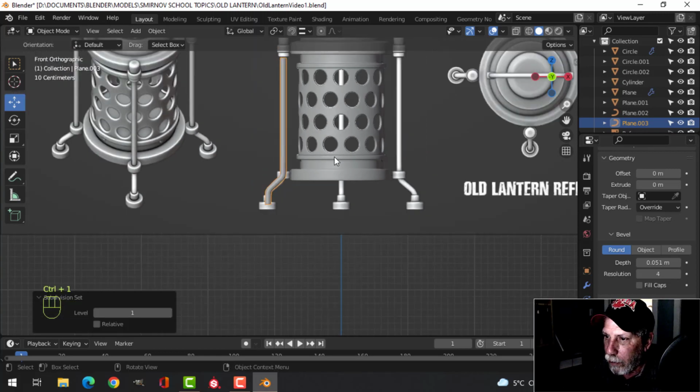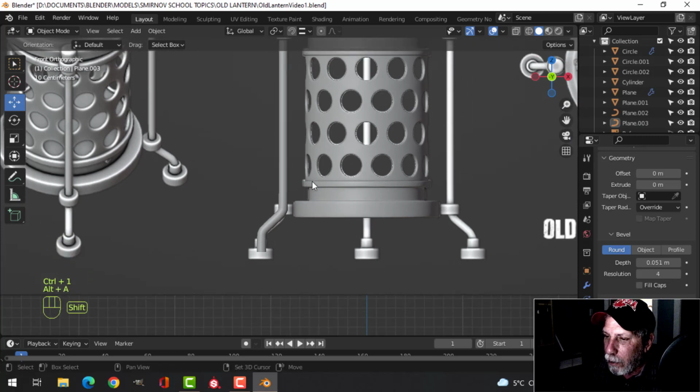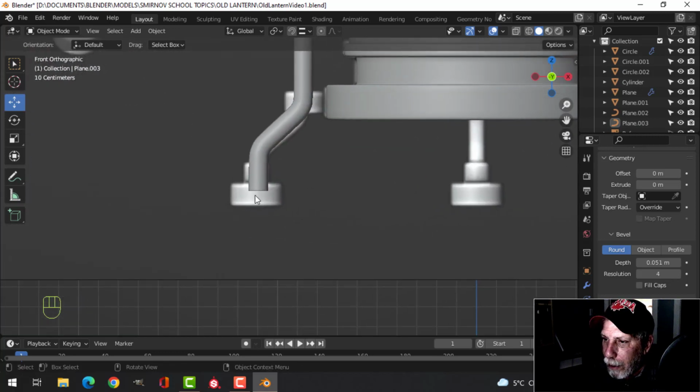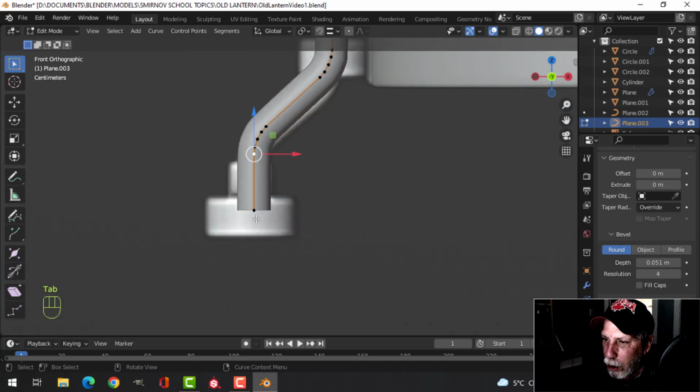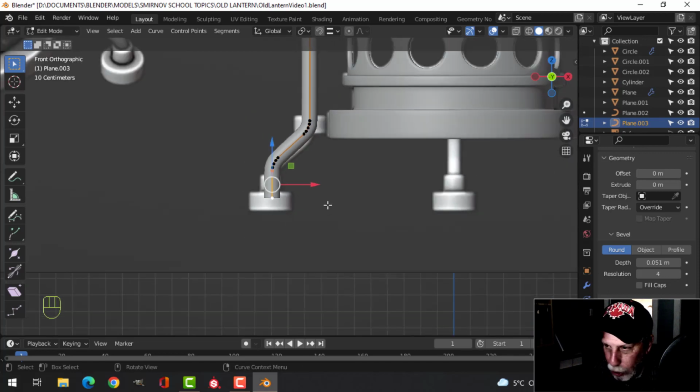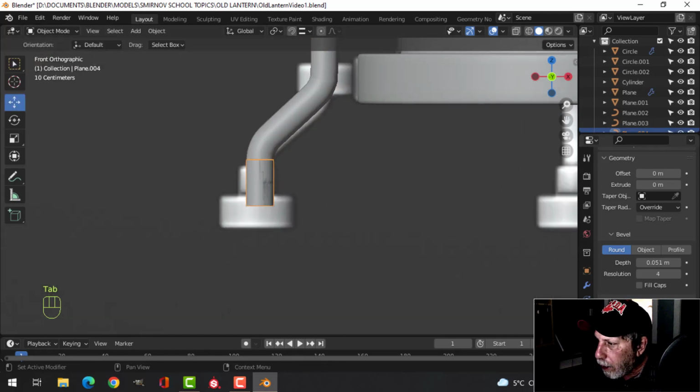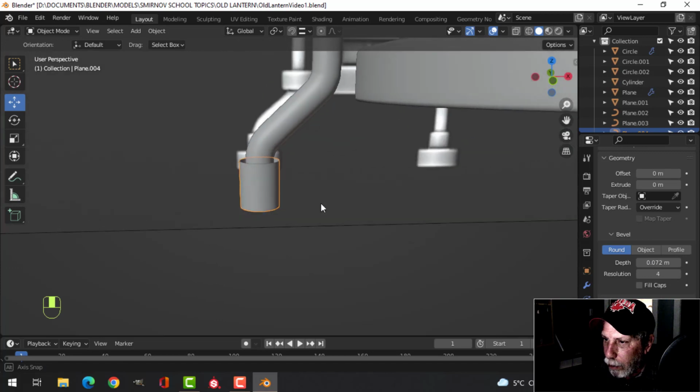You can do Control 1 if you want. And we have that. To make the foot part here, I'm going to select 2 vertices that are in a straight line, Shift D and P, and now you'll see that you have another piece there, another curve. Increase the diameter of that one. It doesn't matter if you're off the diagram a bit. Alright, so it looks like that.